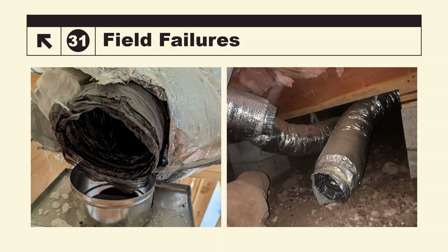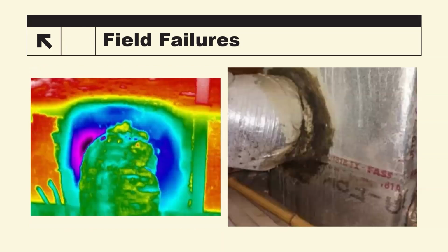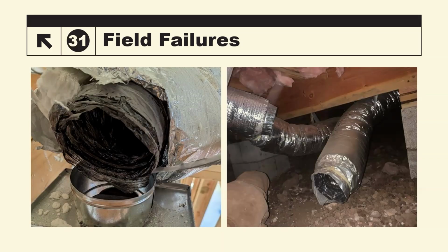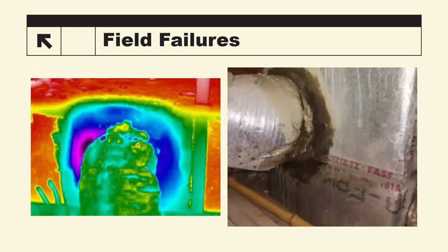It looks sealed, but it's not. And then the one on the right is just disconnected in the crawl space. So just using tape and a zip tie and no mastic on those collars, not a good sign.